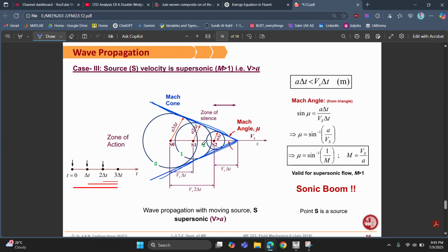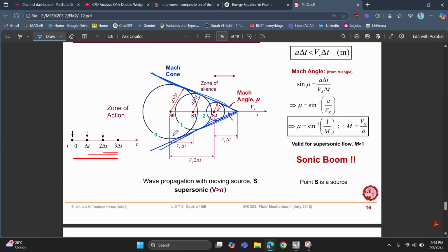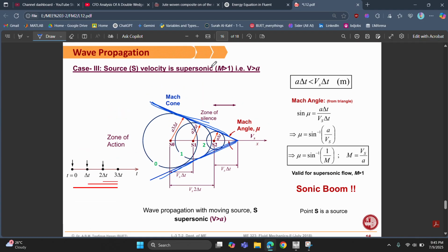We will also discuss this later for the simulation. Also here we consider the flow to be inviscid because the Reynolds number is so much higher for aircraft wing velocity, and the viscous effects are very negligible here. That's why we consider the inviscid flow model. So our main objective is to simulate the aircraft wing velocity for creating a Mach cone, for Mach number 3. So that is supersonic velocity.